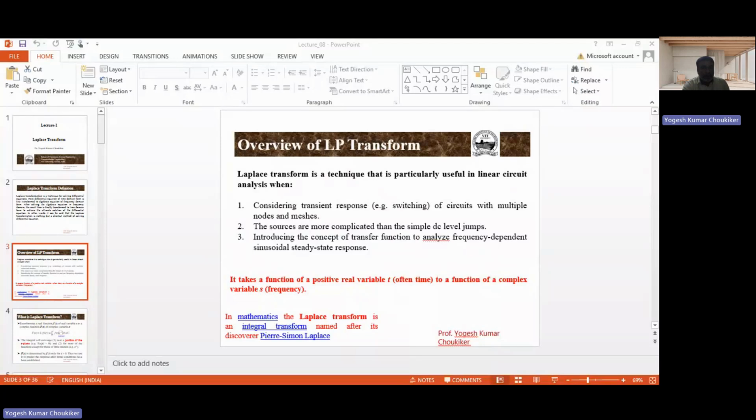So with the zero initial value, we have only the SL value, where SL means in the frequency domain. Apart from that, if you take a Thevenin to Norton, you can see here that SL for the inductor is in parallel with the current source. The current source value is I naught by S.